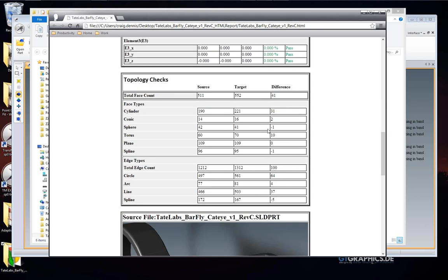So this is where we calculate the number and types of surfaces. Now topology, it's good to know, but it's something you don't want to put a lot of weight into. For example, when we're going from a native SolidWorks file, this applies to CATIA V5 also, they deal with periodic analytics. So these are spheres, cones, torus, cylinders as whole cylinders, or whole periodics are called, whole spheres, etc. No seams. When you save a file out to STEP, the STEP format requires what's called a split periodic, and that basically just means the surface needs to be split at 0 and pi. It's not a quality thing. It's not an issue whatsoever.